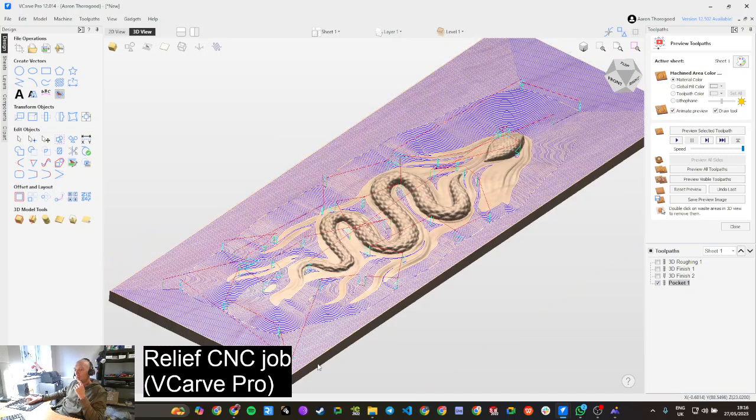So in retrospect, I should have had a very specific position at which I was going to be using the probe plate, and also whereabouts the tool lands on exactly the probe plate. So if I'd measured or made a note of the coordinates when I was probing, that might have helped me a bit. Other than that, I can't think of anything else, and that'll probably save me about a day. And if anybody else watches this, maybe it'll save you a day.